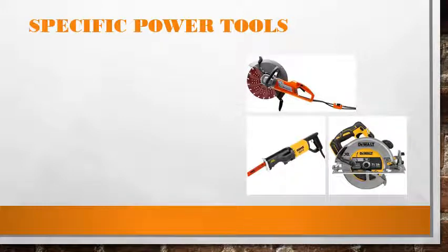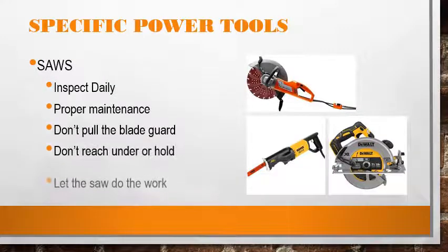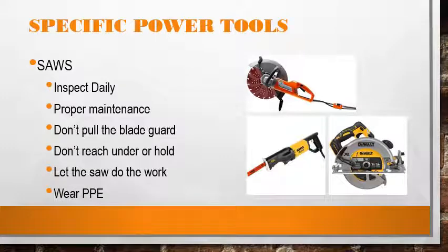When you're using a saw, inspect it. Make sure it is properly maintained. Don't pull the blade guard back. Don't reach under or hold the saw underneath. Let the saw do the work, and always wear PPE.